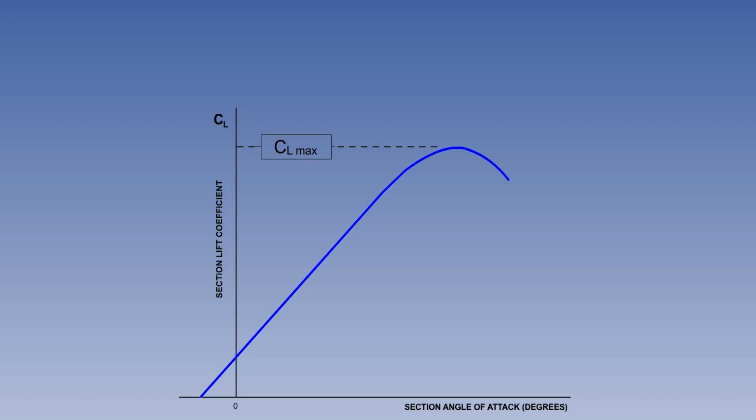The greater it is, the lower is the minimum flight speed or stall speed, Vs. However, the thickness and camber required for the low Vs will also produce more form drag and larger twisting moments at high speed. A high CL max is only one of the requirements for an aerofoil section, but its main point is that it gives a low minimum flight speed.